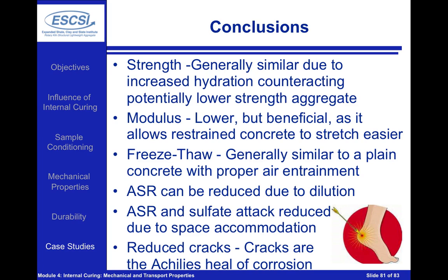We're getting a slightly lower elastic modulus, and you may say, well, that doesn't sound like it's good, but a lower modulus is beneficial because it essentially makes the concrete easier to stretch, if we think about it in that way. So when concrete is restrained, we're getting a lower buildup of stresses in the system, which is going to make it less likely to crack. Lower modulus also means we're going to have lower microcracking taking place in the system.